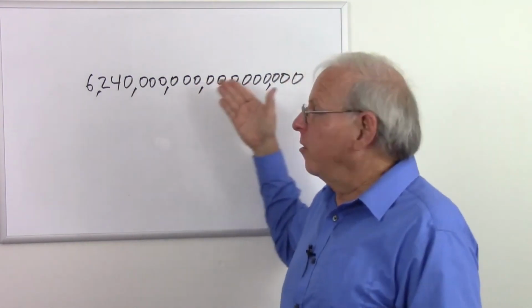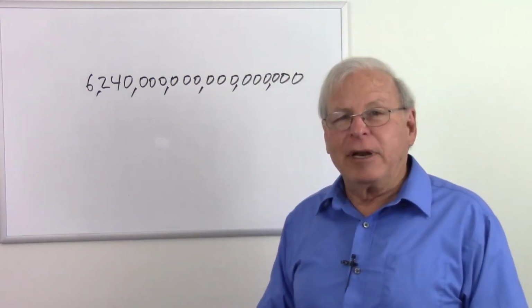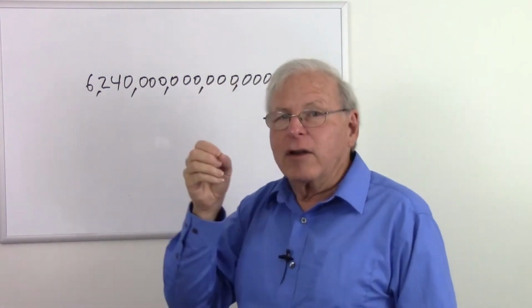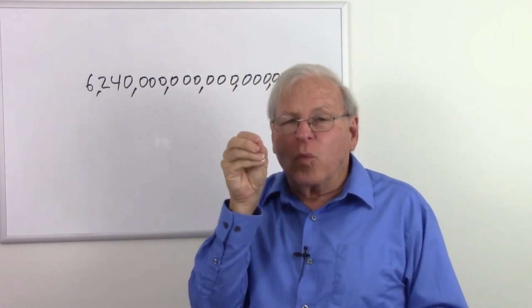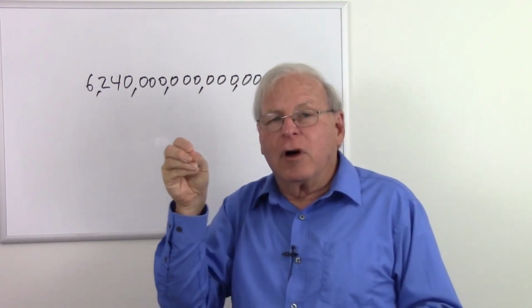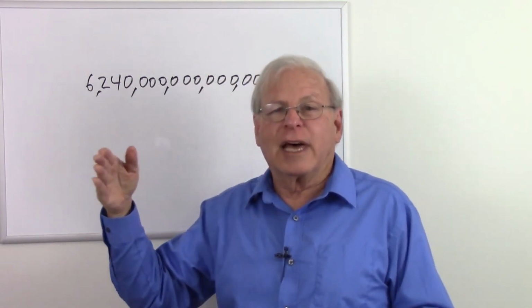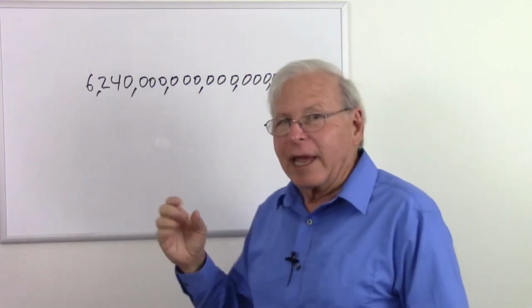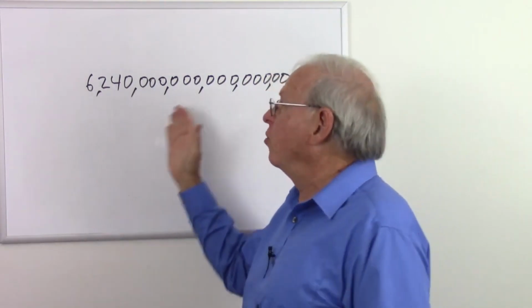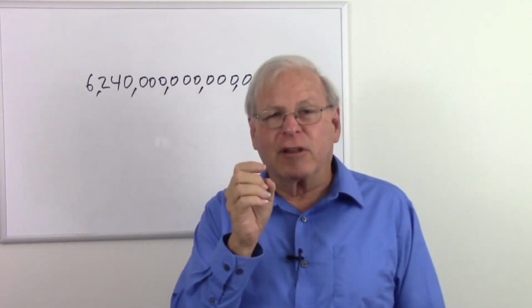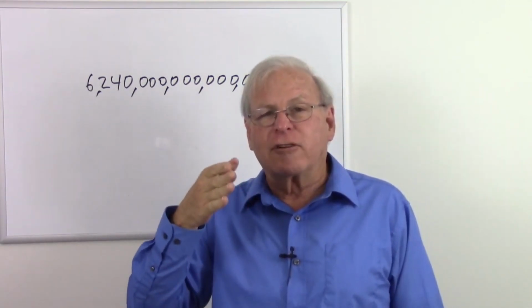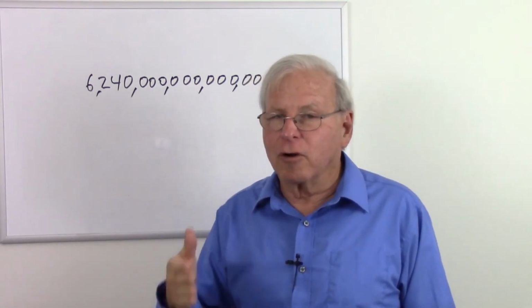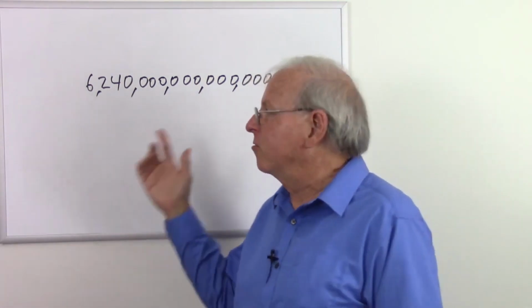So we say 1 amp of current is this many electrons per second. How many seconds does it take for that space of electrons in 1,000th of an inch to move all the way across? Well, it takes, of course, 1,000 seconds, and that would be about 16 minutes. So by simple calculation that anybody can do, I can calculate that it will actually take about 16 minutes for the electrons to move 1 inch, or roughly 2 centimeters in the wire.